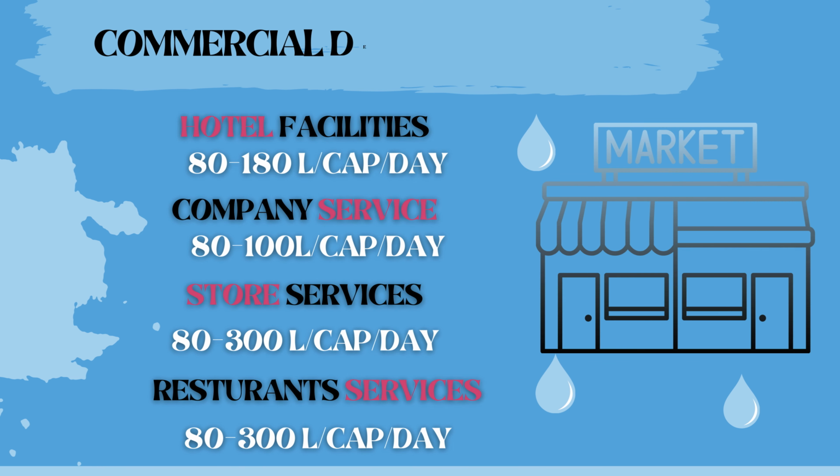Commercial demand. Imagine a busy city. Shops, offices, and restaurants all need water. Here is a look at how much water some commercial spaces might use per day. Hotels use 80 to 180 liters per person per day for laundry, guest needs, and maintenance facilities. Offices and companies might use 80 to 100 liters per person per day for restrooms, cleaning, and basic needs.